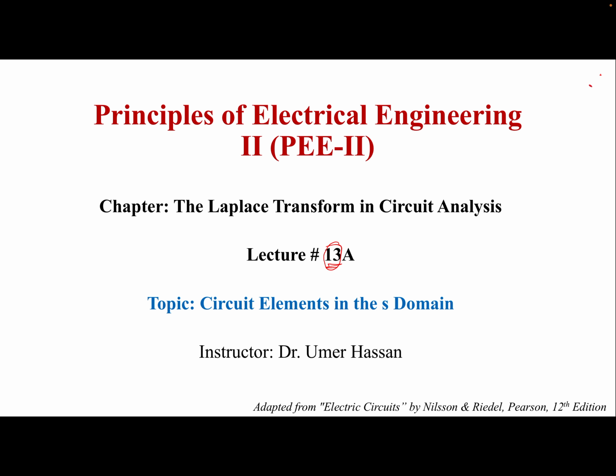We finished chapter number 12 in the last lecture, and in that entire chapter, over 2 weeks, we talked about what is Laplace transform. We solved so many integrals, and we applied Laplace transform to the functions and to the operators. We also did one circuit example, but this chapter is all about circuits, and how to apply Laplace transform to the circuits and solve all of those circuits. So we're going to solve a lot of RC, RL, RLC, natural and step responses through Laplace transform, heavy-handed, in this chapter.